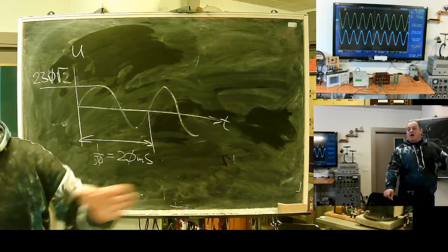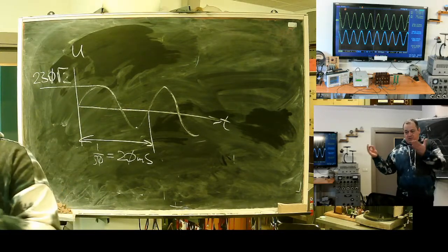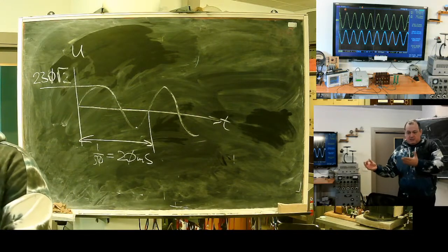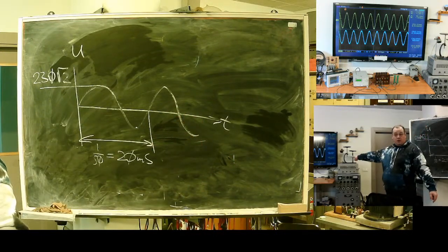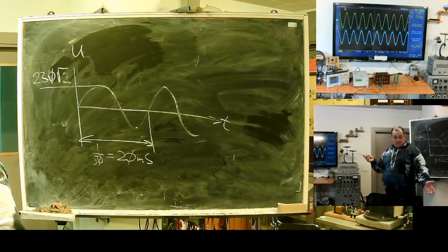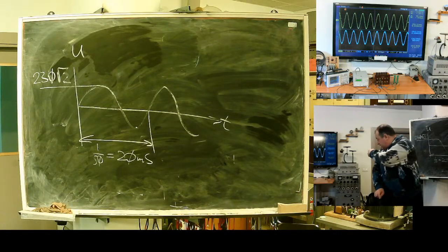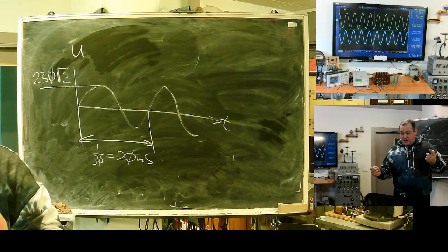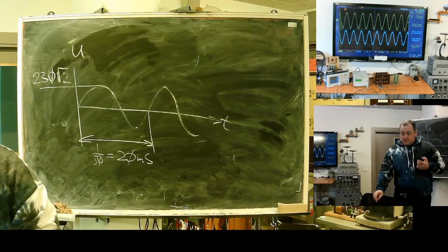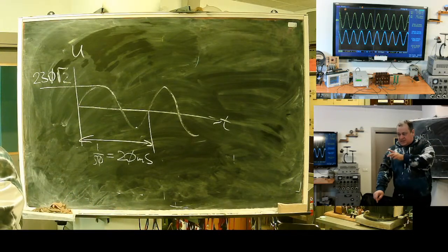What will be equivalent in AC? AC voltage producing as much energy as DC. Let's say I load this battery with the 600 ohms, it will produce some heat. Equivalent, if I take another one and connect to my generator, when will it be equivalent? When this thermal power will be equal. It's called RMS or effective value. DC voltage producing as much energy as its equivalent AC.